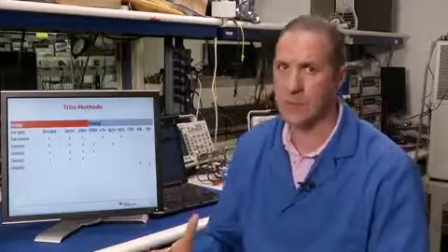85 nanovolts is not that uncommon, whereas with an E-trim device, it's really upwards of 100 nanovolts, perhaps even reaching up to 500 nanovolts. So you see the difference there. I'm saying this because, again, if you reach up to extreme temperatures, consider using a zero drift instead of an E-trim device.